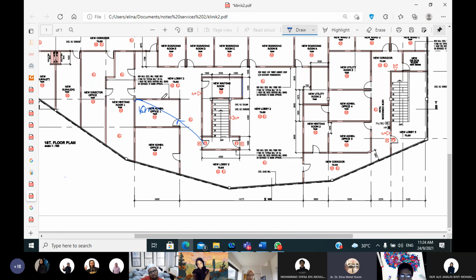So you have to provide another wall with a door, so that from the door here to the end of the room it's 6 meters or less, and from the door to the fire door here, this is accordingly not exceeding 15 meters. So this is, I mean, very near to achieve your fire door. Okay, faham tak up to there?